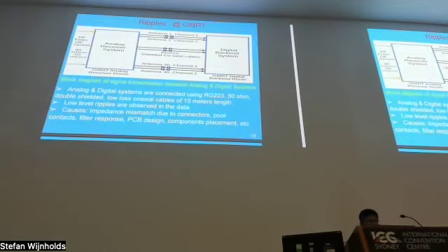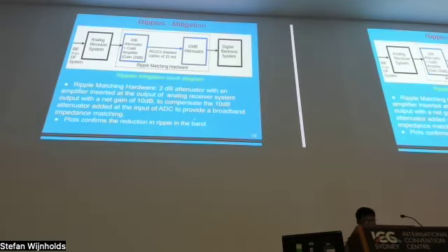So here, as noted earlier, because of the connectors, length of the cable, PCB design, and spacing of the transmission lines, all these factors contributed to low level ripples in the system. So causes are PCB design and components, all these. Then mitigation. To mitigate these ripples present in the system, we have used a 10 dB attenuator.